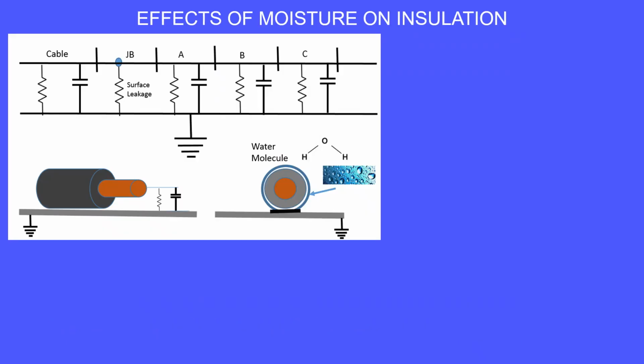Moisture does not drive the insulation resistance down unless there is true insulation degradation or surface leakage. When the megohm result is affected by moisture, the insulation is compromised and the motor is installed in a critical application, we should consider replacing the motor.